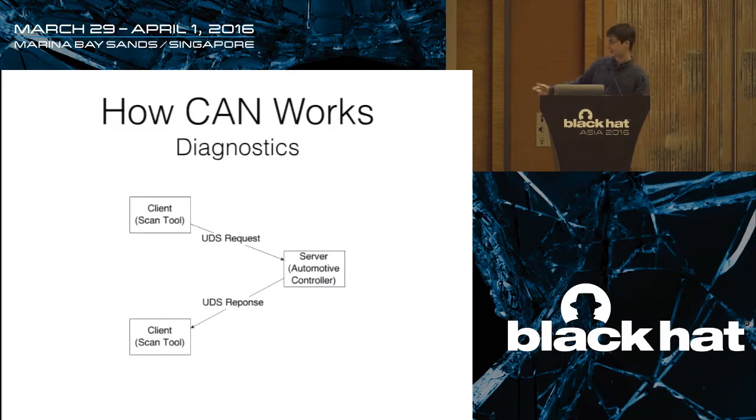So you typically see this as a scan tool, which is what a mechanic is going to be using plugged into your vehicle over the OBD port in the car. It's going to send out a request. That server, which is the actual controller, generates a response and sends it back. And you can chain these together to create sessions. And there's different ways of implementing security for the sessions and all that, but this is the other common application of CAN other than just signal databases.